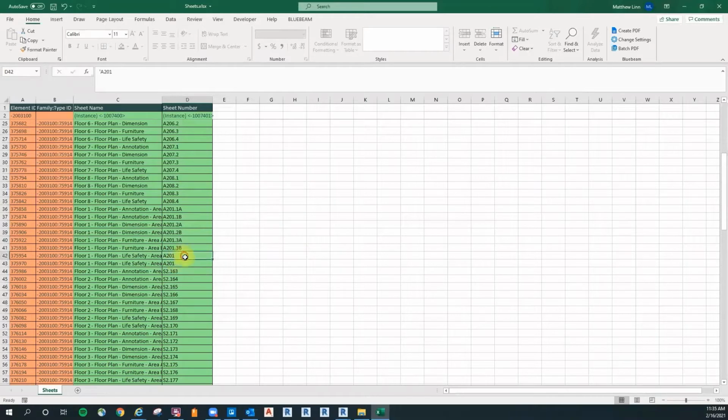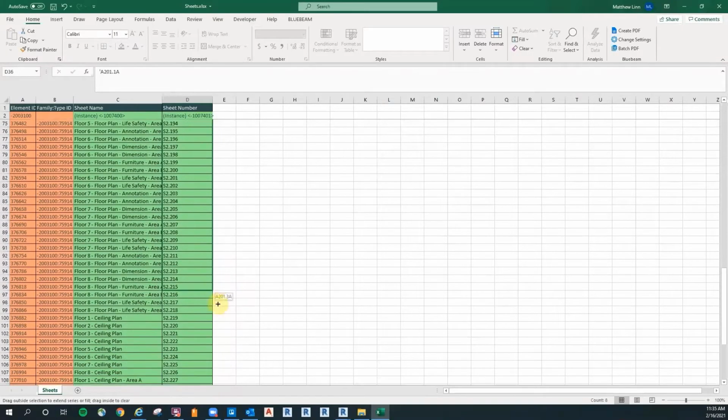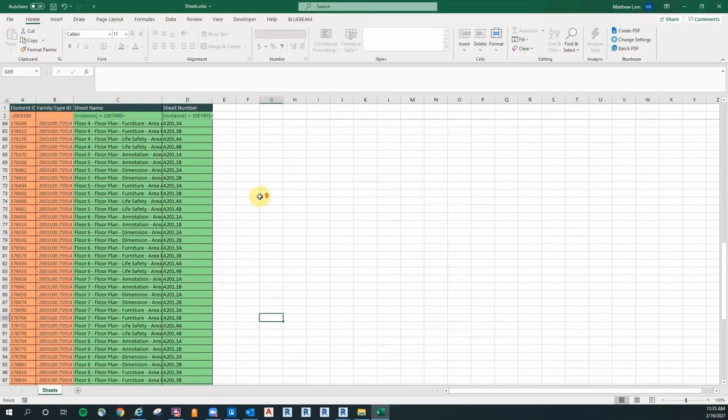And even in Excel, if we were to do this in Revit, we'd have to right click, say renumber, enter that dialog, say okay, come back out and then re-enter it again. Whereas here, we're just going cell to cell. All right, here is where we can really pick up speed. I'm going to grab all of these and autofill for all of the floors. Just like that, it autofilled. It autofilled exactly the same way as it would have been on the first floor because they all end in that 1.